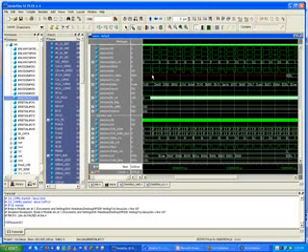You can look in the code. It's putting out the least significant bit first, so you have to read this kind of backwards. 0011, that's the C of this 035C. It's all going out least significant bit first. And then 1010, that's the 5, etc.